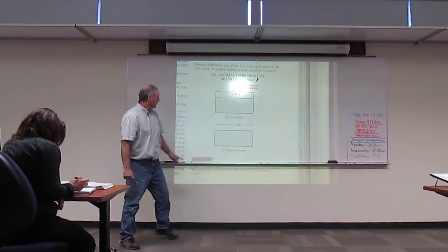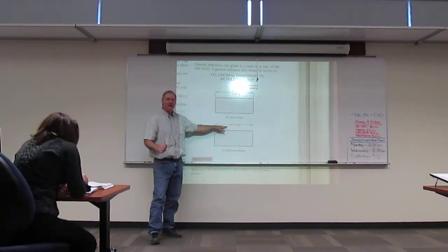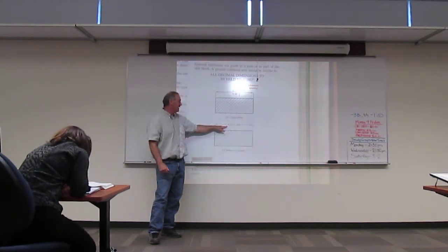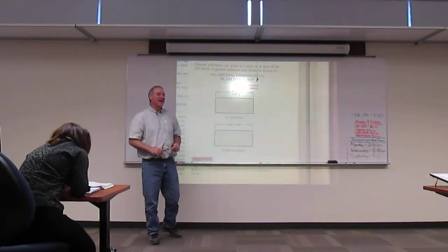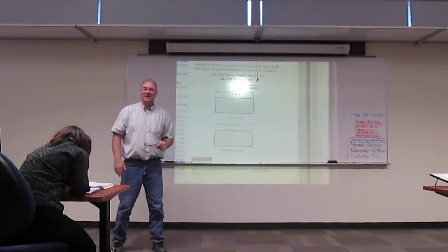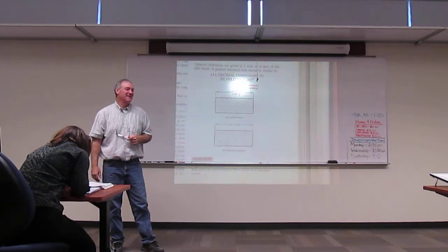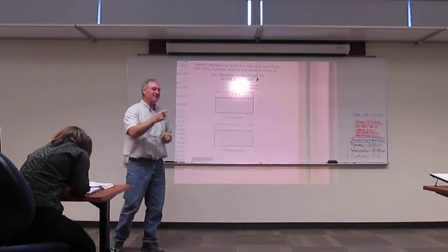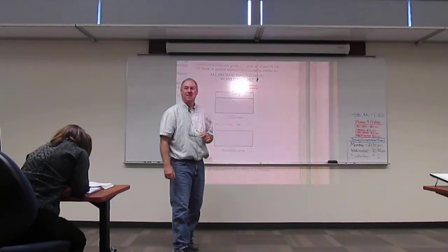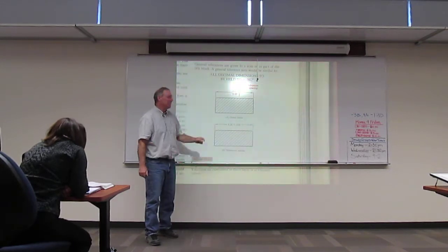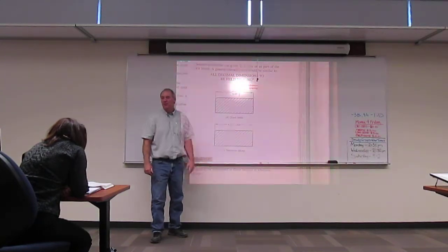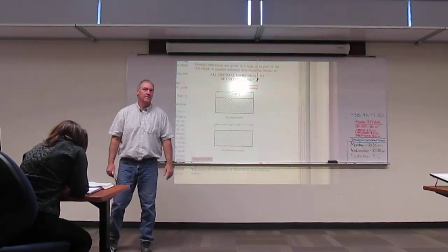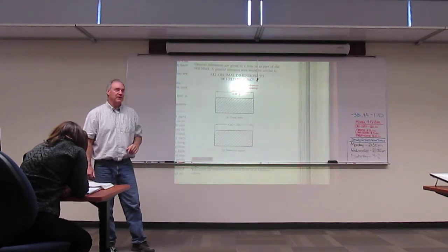Now, one thing I don't like about this example right here, the author kind of made a little bit of an error. Can anybody pick out what the error is on that? I put it on some of your drawings as I was correcting them the day before Thanksgiving. Zeros after the 4. Significant figures don't match up. And this is bad dimensioning technique. This should be 4.000 if I'm going to take my tolerancing to a 10,000th. So you want to make sure those kind of match up.